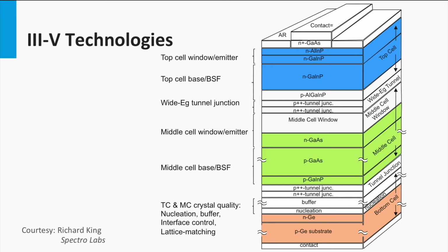How does a multi-junction solar cell work? The p-n junction at the window layer at which the solar light enters the PV device is called the top cell. As the spectral part with the most energetic photons like blue light has the smallest penetration depth in materials, the high bandgap junction always acts like the top cell.